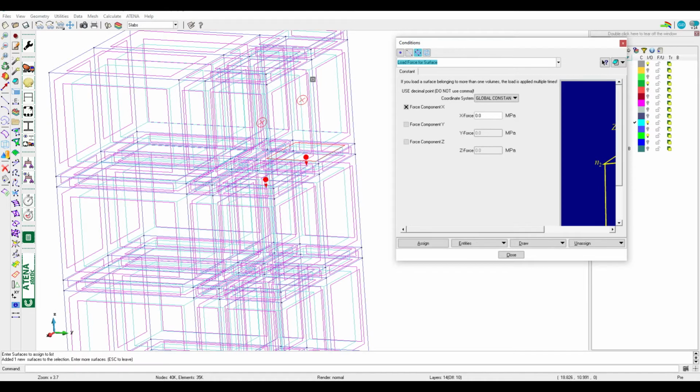When we delete the upper volume, this load case will stay in the input file. So we will get an error message from the software, and the analysis will be interrupted because the software cannot find the element anymore. To solve this problem, we can divide the load by the thickness of the plate, and we can get the body load and apply it for the plate.